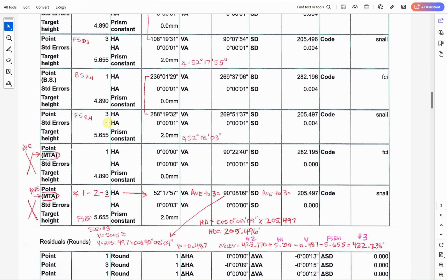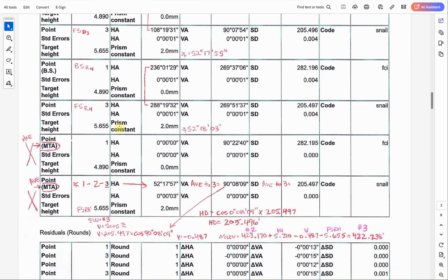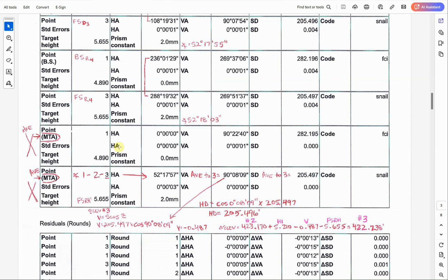You don't need all of that information individually. It's already been measured and stored. What you do need is the average angle at the end of all of that. So look in your report. This is where you're going to find the average angle out of those 4 that were turned. So you'll need to pick that out.